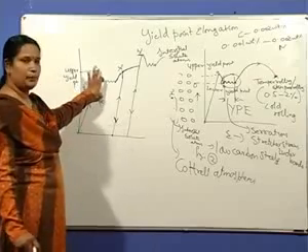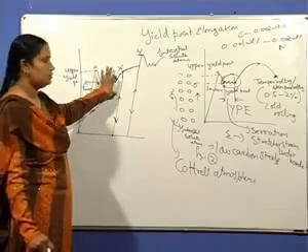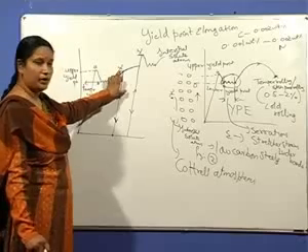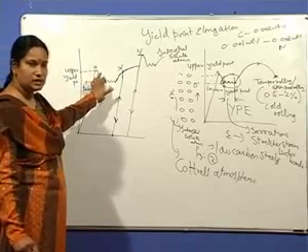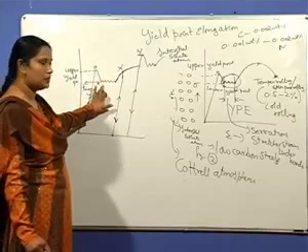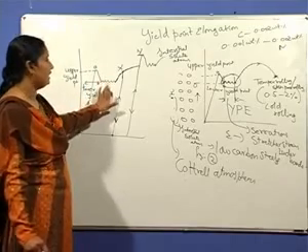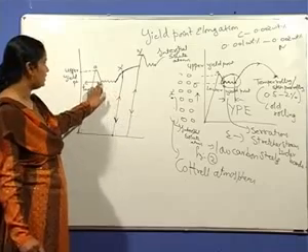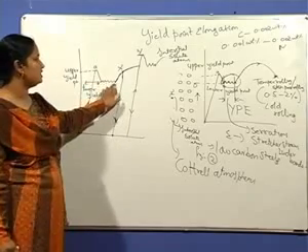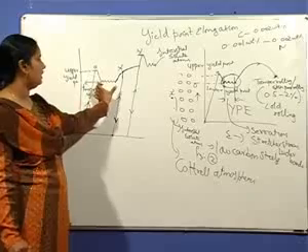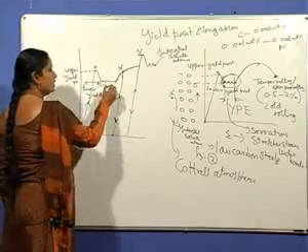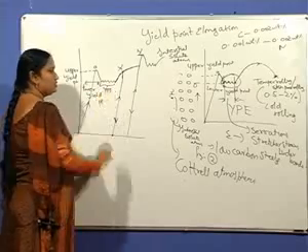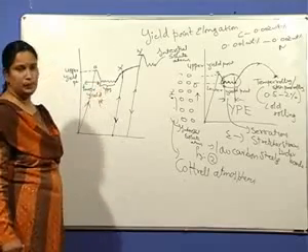Load the material up to the point A. So point A is the upper yield point where the material undergoes yielding suddenly. The stress drops and again the material undergoes yielding at a constant value of stress. Stress is almost constant, but the material has undergone yielding to some extent. So this is known as yield point elongation. Point B is the lower yield point.